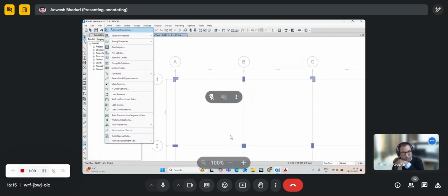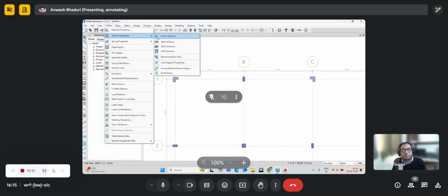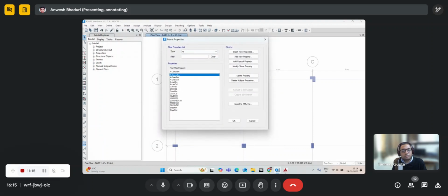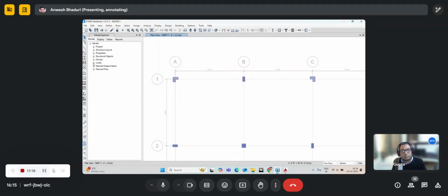So say I define another beam section over here. Or we can use the main beam that is already there. We can just directly use the main beam that was already defined earlier. We go to property. We'll select the MB 300 by 600 section, and we'll draw a beam over here.